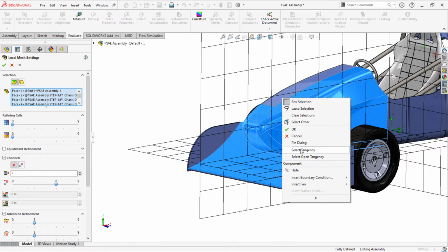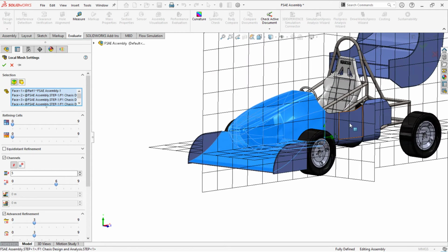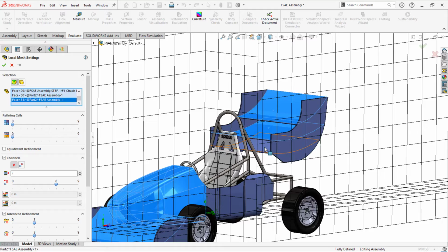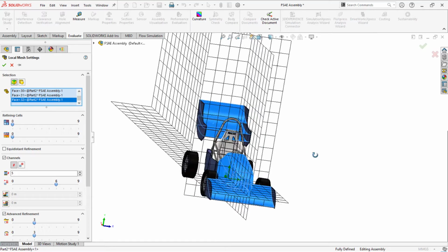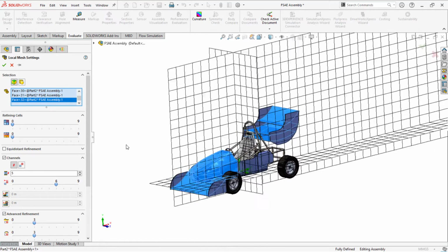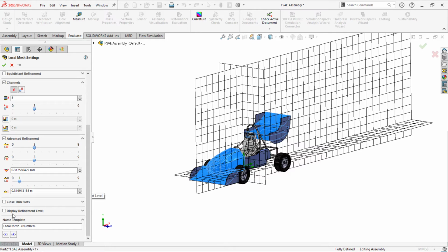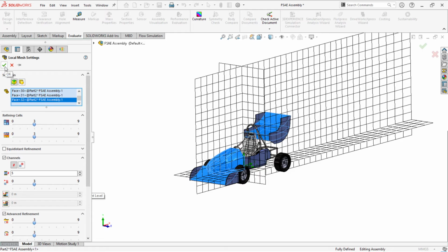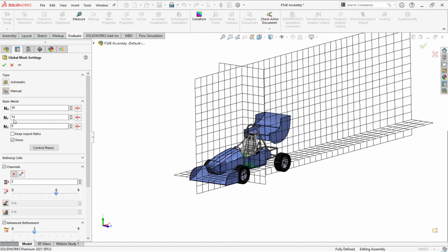Remember, this mesh will take some time, and even the results extraction might be slower due to the fine mesh and the system performance. If you have a better system, you can run it within a short span of time. So I'll set it to level 3 of the requirements, and okay, no issues. You need to have a better experience on the meshing side if you want to deal with this kind of advanced meshing. And this is the automatic fluid mesh.